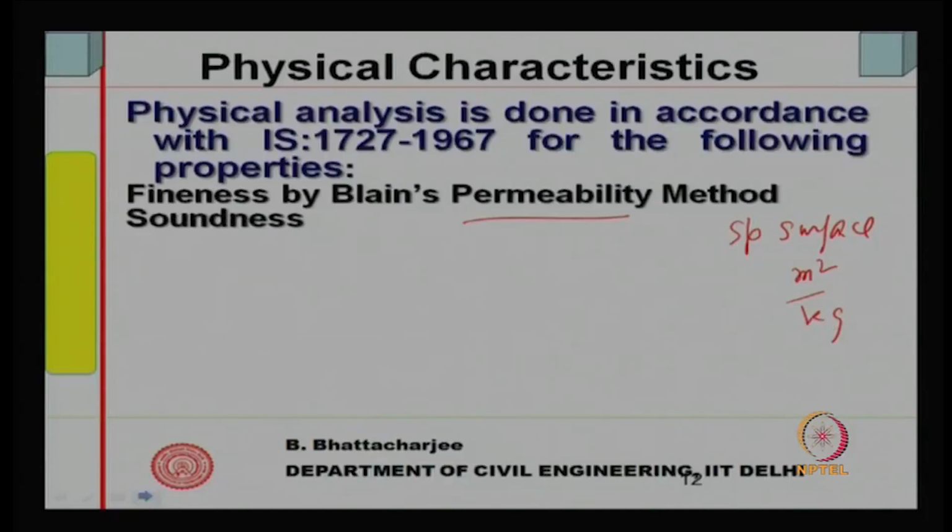We measure soundness like we do for cement: is there any volume change with certain reactions? Lime reactivity is an important test, whereby we measure in fact the pozzolanicity. What we do is we make cubes with lime, pozzolana and sand.